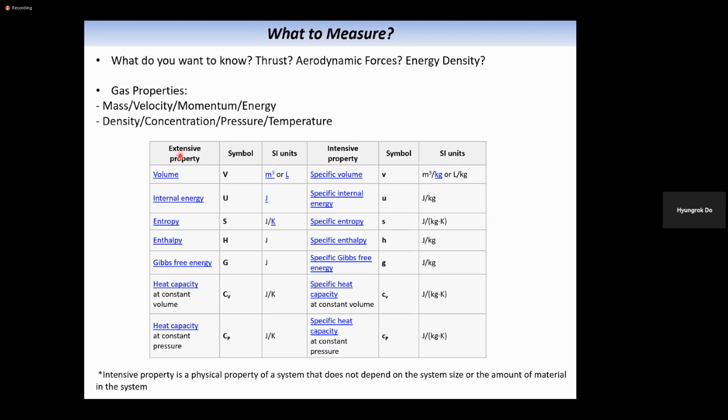So usually the optical measurement method can be chosen for measuring velocity, density, concentration, pressure, and temperature where sensors are not working. It can be a cheaper way of measuring that. But with propulsion applications, or high energy, high performance, and high speed vehicles or high performance systems, mostly sensors will not work. Recently, new sensors have been developed, and some sensors are working at high pressure and high temperature conditions.